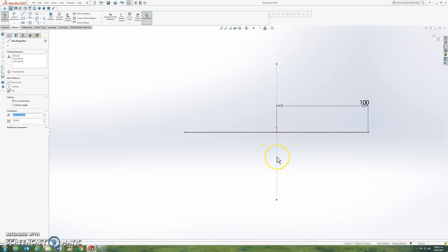Okay, I'm going to right click on the center line, go down to select midpoint, holding the control key. I'm now also going to select the origin, and say that they're coincident, which means they're touching each other or on top of each other. Just OK. So whatever distance this is high, it's also projected out the bottom the same distance.